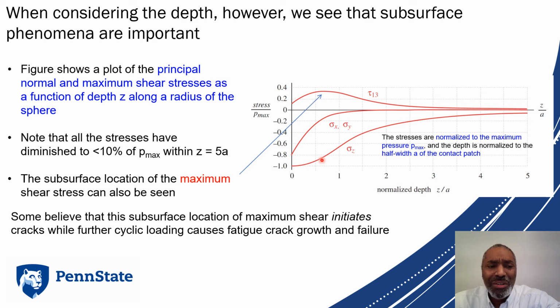And once this occurs over time, we can reach a limit cycle in which we can predict where these things will fail. And that's one of the ways that people begin to analyze ball bearings or any sort of rolling metal structures. So it's kind of cool that the subsurface stress leads to failure under the surface. It's exacerbated by normal stresses, and then it's evidenced by the failures that we see, cracking or pitting on the surface after the fatigue limit is reached.